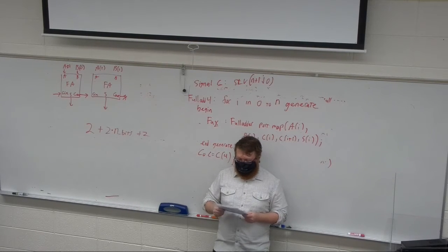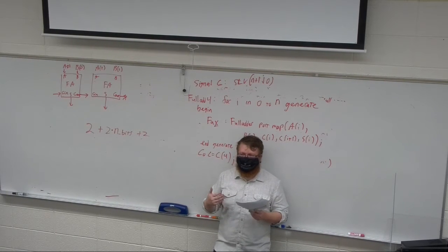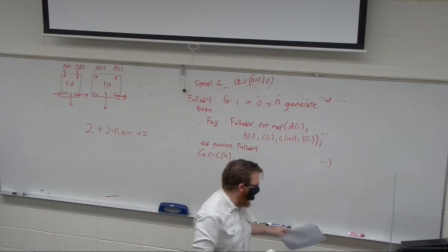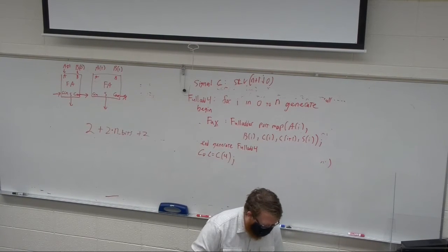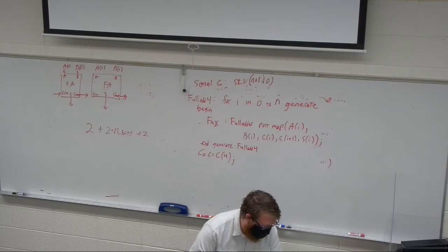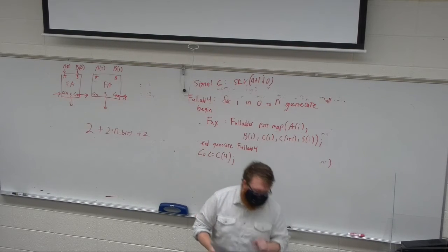Number 13, this one was a nightmare to grade. The way that I did it is I essentially went through and made sure that it was microcode compatible first off. So that's page 287, where it just lists 2 bullet points. Eliminate all conditional outputs by transferring to the core machine, and then make sure you test only 1 input in each state.